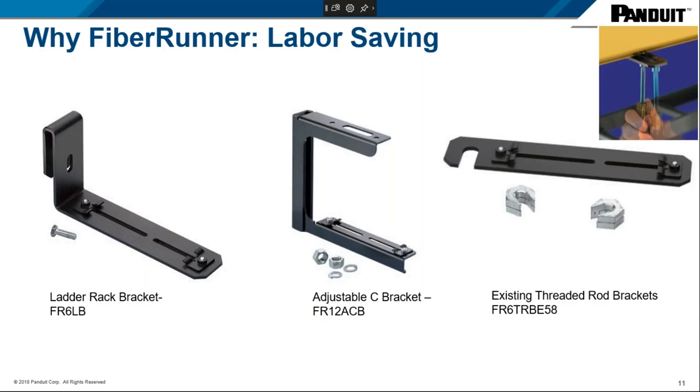With the brackets that we designed, we have those clips that we're showcasing, and as you're going to see on the far right, we show a picture of somebody just going to the bottom of this and tightening down the bolt. Again, these clips just slide through and connect to the channel. So again, just one tool does it all to tighten the channel to the brackets themselves.